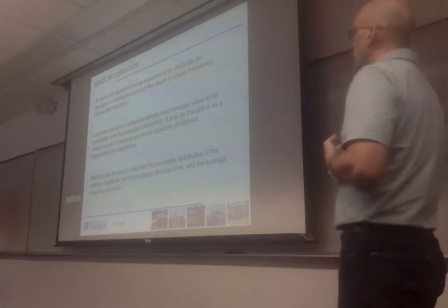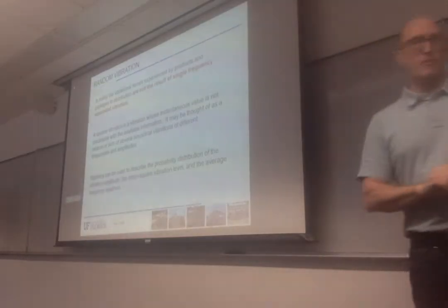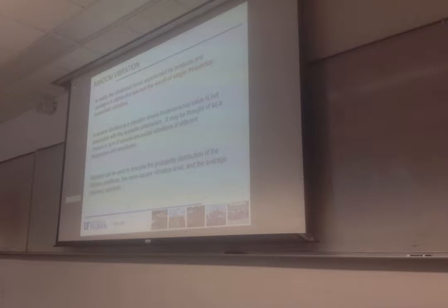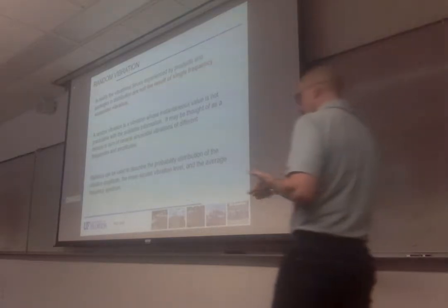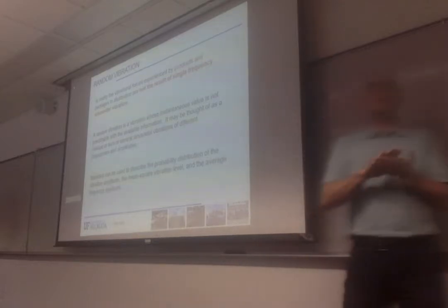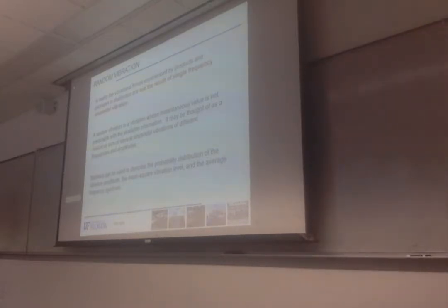A random vibration is a vibration where the instantaneous value of acceleration, and therefore amplitude, is not necessarily available information. It's a mixture of a bunch of these sine waves all put together. That means typically statistical distributions are used to reproduce those vibrations or analyze them. This is what is mentioned at the bottom.